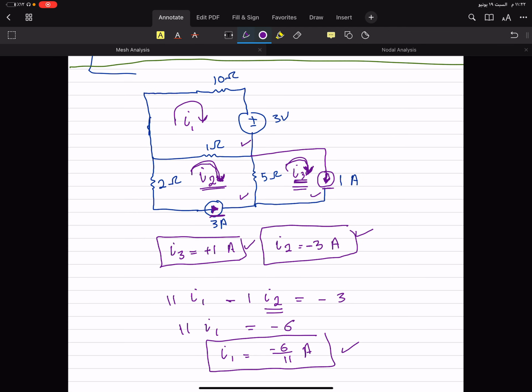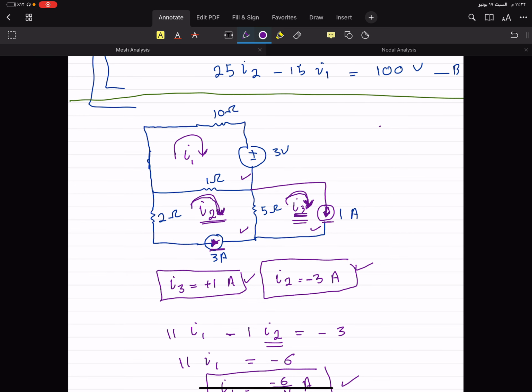So when you have mesh currents, as we had in nodal analysis, when you have a voltage source next to a node, let's say this is a node, and this is a circuit continuing here, and this is the voltage source, it's 10 volts. Since these two are parallel, the voltage in this node and in this resistance is equal to this 10 volts. I explained this point in the last tutorial. You can come back and check. So it's the same here.